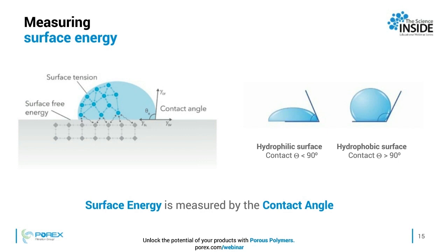For example, polyethylene, PE, has a surface energy of only 35, versus water, which has a surface energy of 72. In that case, water does not wet out PE. Replace water with alcohol, which has a surface energy of only 24, and there you go. Alcohol can actually wet out the PE surface evenly.